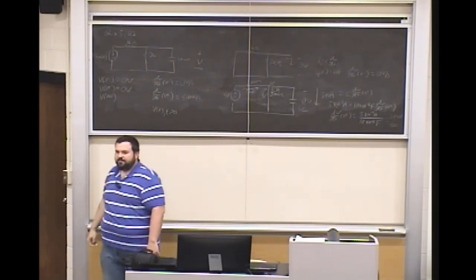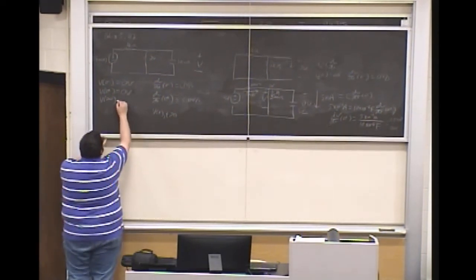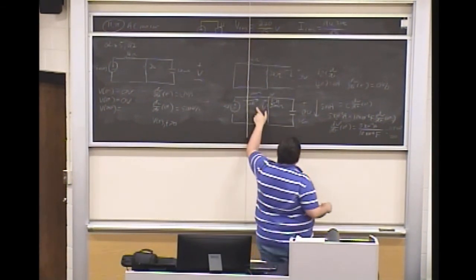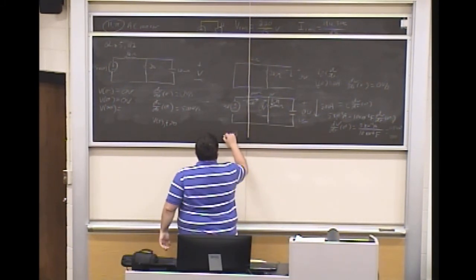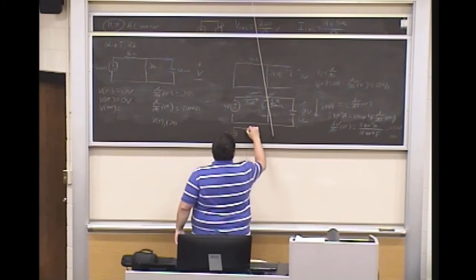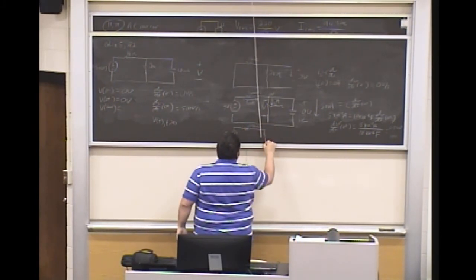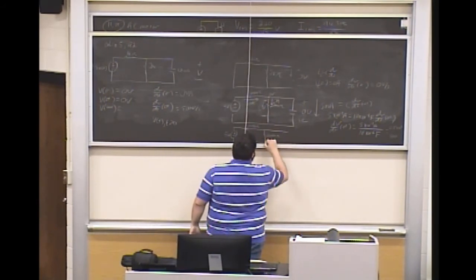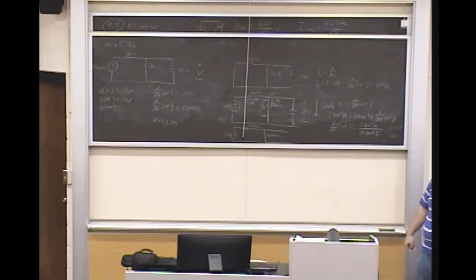That makes sense? And then our last part over here, V at infinity, we have to yet again look at what this is going to behave like as t goes to infinity. This is going to be a 5 volt source. Now's the time for our old friend, the voltage divider, because now the capacitor behaves at steady state again like an open circuit.